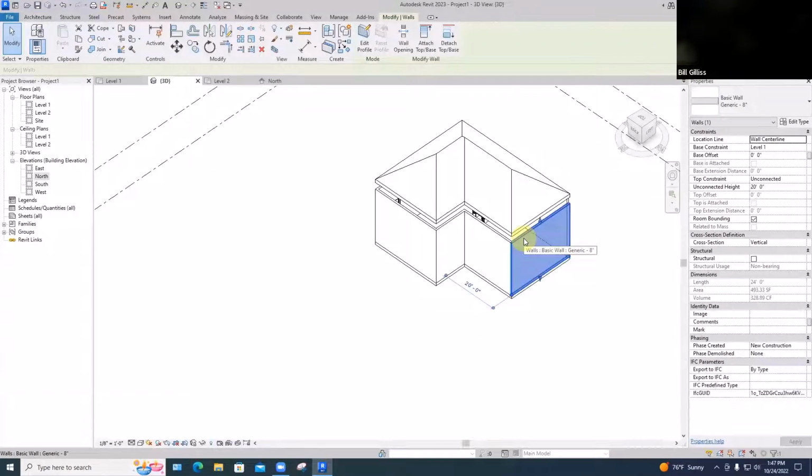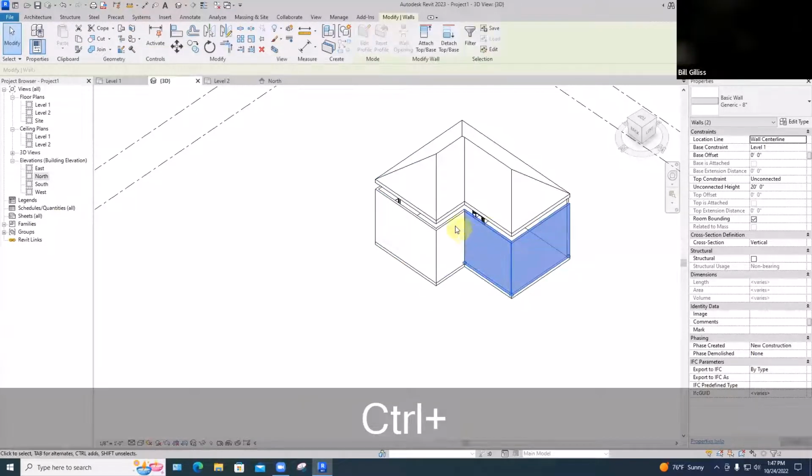When you're selecting things with AutoCAD, you can just sort of keep picking things and they'll all be selected. With Revit, you have to be explicitly saying, I picked that, and now use Control Pick to select any others you want to select.